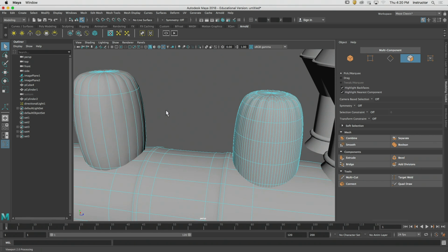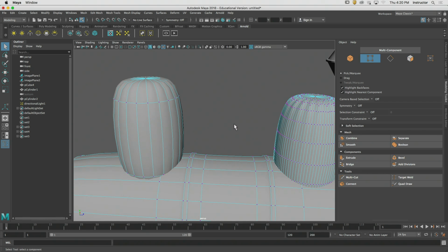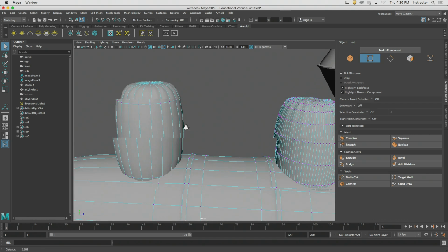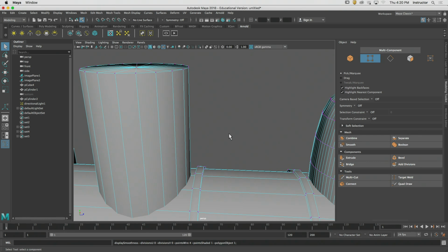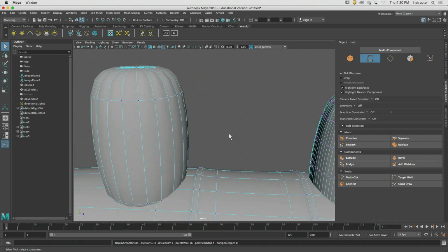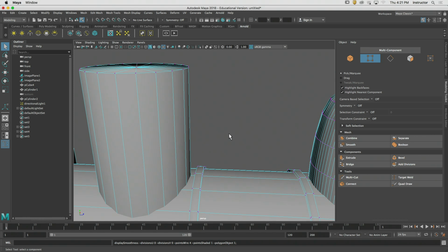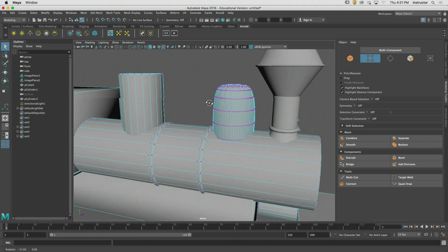If you check out this cylinder over here, and I've done it across the entire object, unfortunately, that's okay, but I can always go back. So sub-Ds allow us to smooth shapes out. We're going to talk about how we can control this and how we can take advantage of this next week, but then we can go back to an unsubdivided shape and continue working. Okay, more on that next week. A little preview of next week, subdivision surfaces. It's going to change your modeling world. It's awesome. Okay.